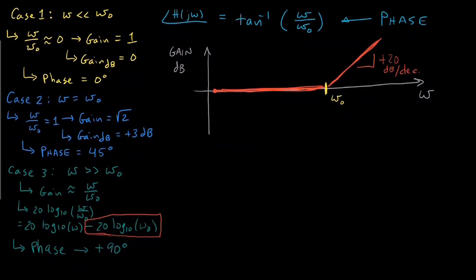So really what's going to happen is our curve is going to start close to 0, move along like this, and miss this corner by a little bit, and then go asymptotically toward that red line. It's going to be very close to parallel to the red line here. It's going to make a little more of a curve instead of an angle here, and then asymptotically approach the red line. And the difference between here and here is approximately 3 dB.